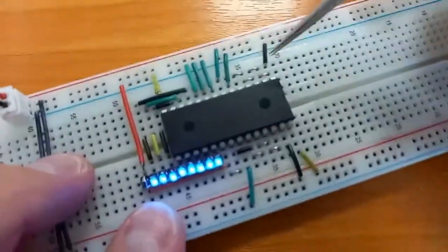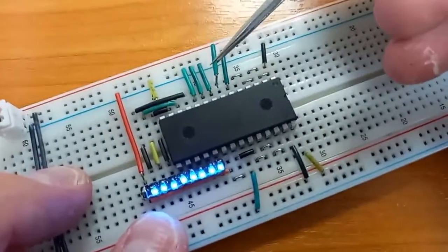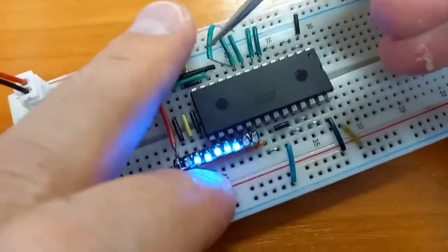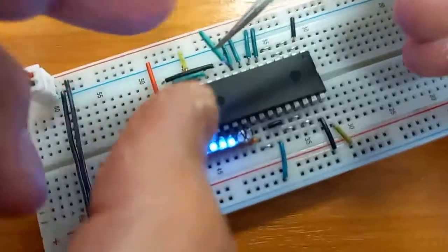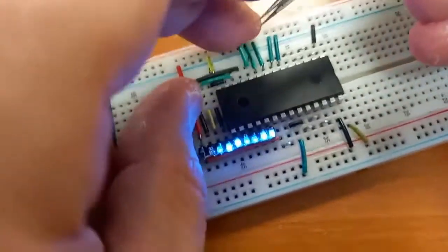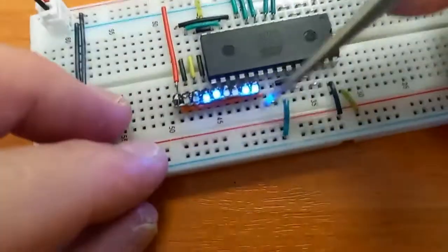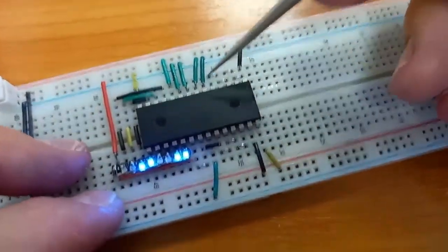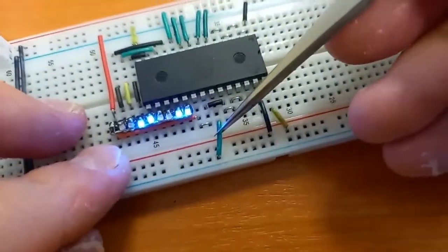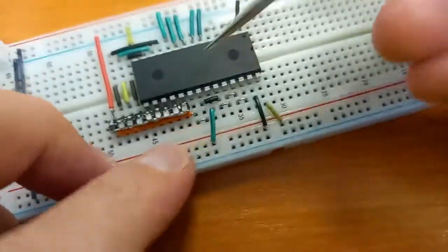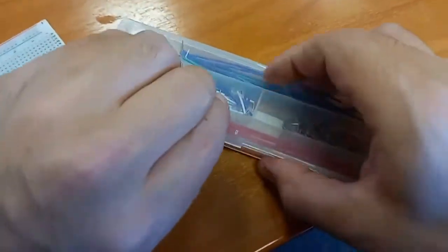So now we're going to change the address to 1, because at address 1 lives CC. We don't want this CC, we want number 1 there. So at address 1 we have CC, 11001100, that's CC. And instead of CC we disable the output now, and instead of CC we're going to set here 1.